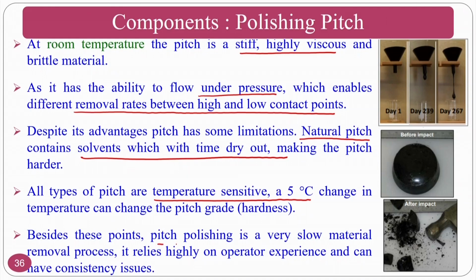Besides this, pitch polishing has a very slow material removal. That means that the specific energy requirement for pitch polishing will be very high. The material removal is very slow, but the input energy is very high. This is also one of the drawbacks of polishing pitch.